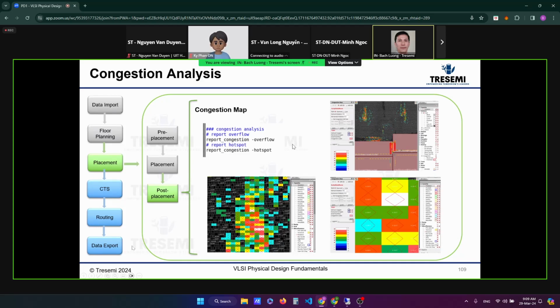So the tool will help you, right? The tool will help you display where the congestion is, and you can zoom in. For example, I zoom in on this particular G cell, right? You can see here, actually take this one. This is vertical congestion at V, so it needed 20 tracks. This is the number needed, and 17 is the number of availability. So they need 20, so this is 3 over.